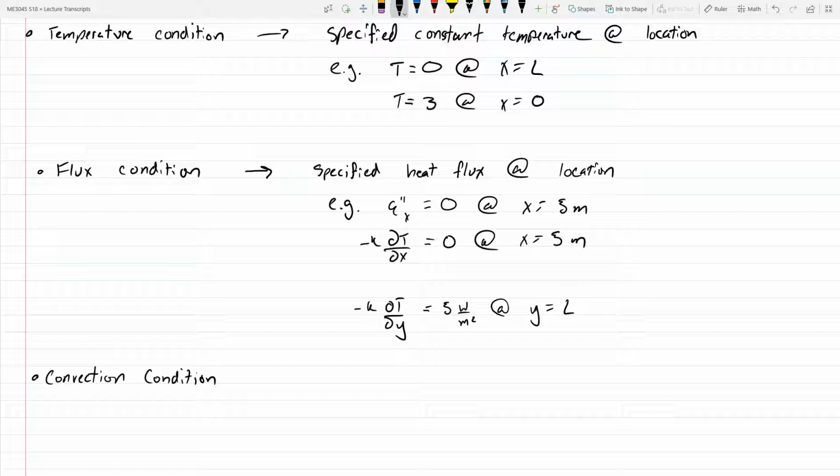If we have something that describes the way that, or the heat equation can be used to calculate the way that heat travels through a heat sink that's embedded in the back of a phone, what is happening to that thermal energy once it reaches the back of the phone is it's in contact with air. Right? There's this convective cooling at that point. That's the case with really almost any sort of heat sink: it travels throughout the solid according to the heat equation by conduction, and then gets dissipated from there using convective cooling.